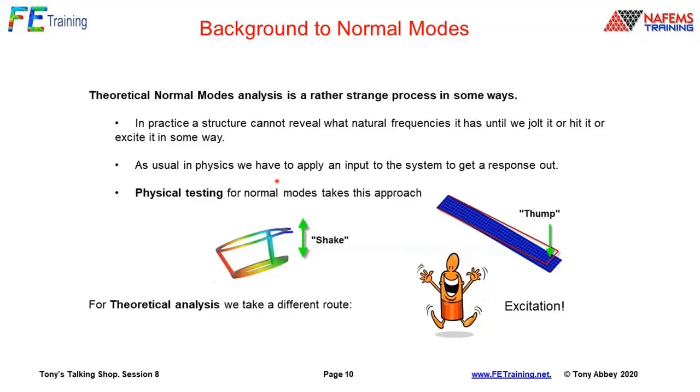In practice, if we want to find out what natural frequencies are in a structure and we go for physical testing, then we've got to either shake that structure, so like a coffee cup holder. This is just a sort of like a diving board. We've got to thump it. We've got to put some form of excitation in to actually see what these frequencies are. And we're not going to pick them all up, because those that are just lying around not going to get excited, we won't find them on test. We will find them on a theoretical analysis.